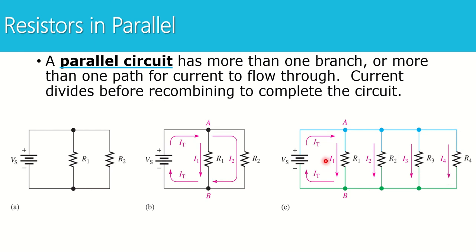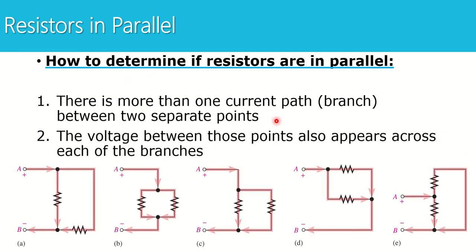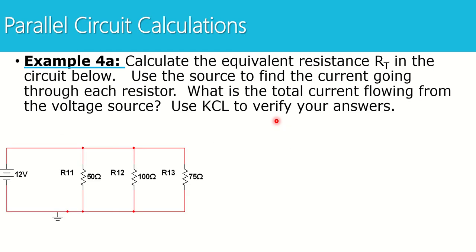That means that the 4 paths must have the sum total of what went in. Or in this case, if I had 2 paths, if I had 50 milliamps going into this node, well, some goes this way and some goes that way, but when I add those 2 branches up, I'm going to have the same amount of current that I started out with before it split. That's KCL, Kirchhoff's current law.